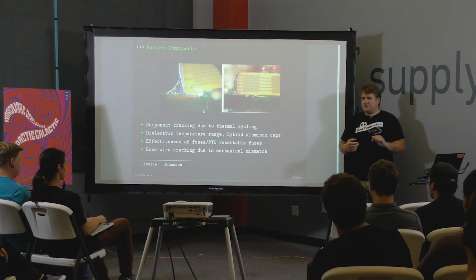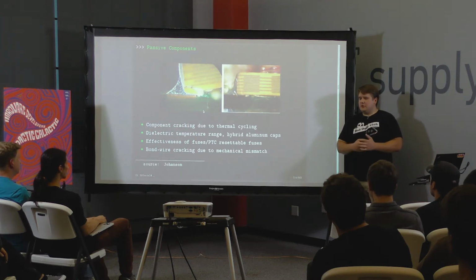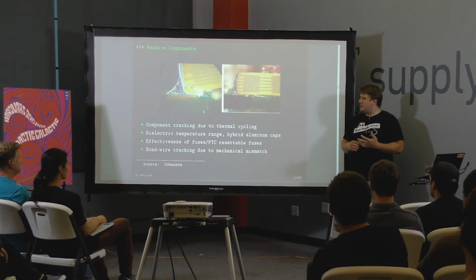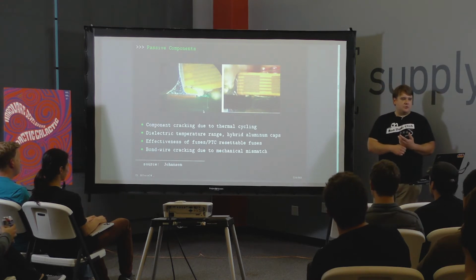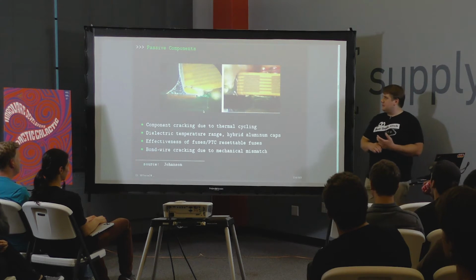Dielectric changes with temperature. If you have an electrolytic capacitor, it's going to vary wildly, and in some cases, depending on what kind of crazy ferrite material you're using for a core, inductors can change as well. So you have to keep that in mind and either design for it or test.